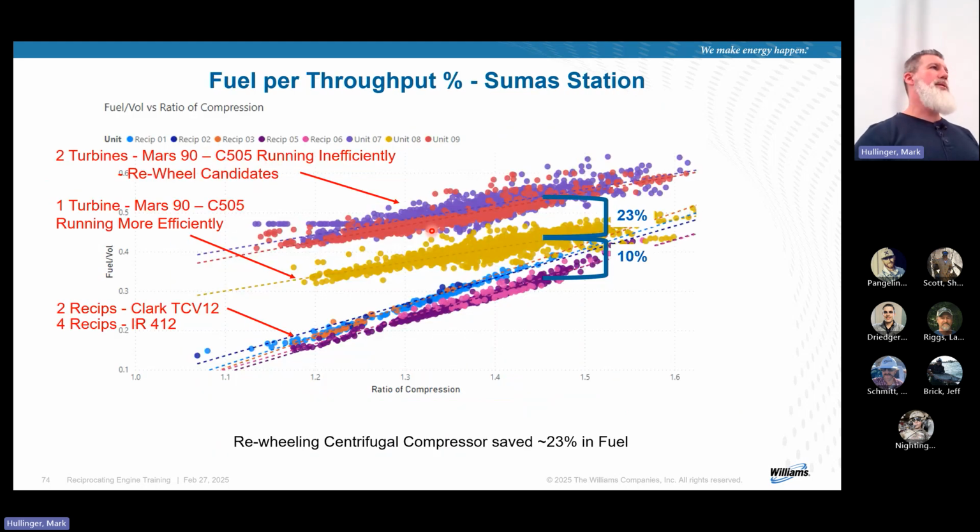So that's one of the reasons when we're looking at combusting with NOx and methane slip, turbines have very little methane slip, almost 0. Unless you really lean out or put some nice controls on a recip, which costs a lot of money to retrofit, then you're not going to get that. You're going to still have a little bit of slip, but you lessen it a whole lot. Thanks, Ryan.